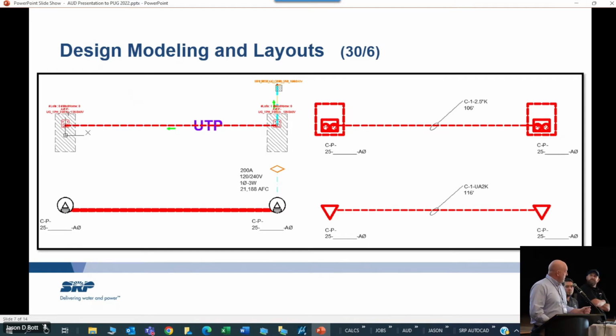So in the upper right corner, that is a view of our conduit 1 line. In our system, when we have a new project, the customer digs the trench, puts the conduit in. So that 1 line is the instructions for them to do the job correctly. The lower left corner is our main line. Basically, it actually looks a lot like how the GIS will look once the GIS is populated. But this is the physical location of where things are in the field, so the crews can drive to the transformer, drive to the location, right? And then the lower right corner is the electrical schematic, which our engineers care about.